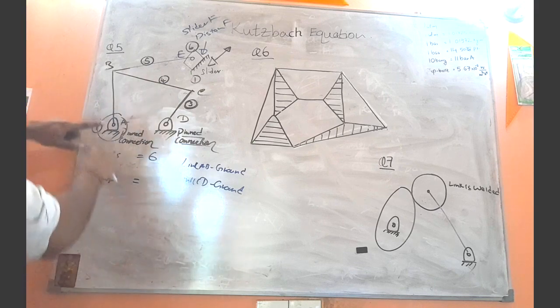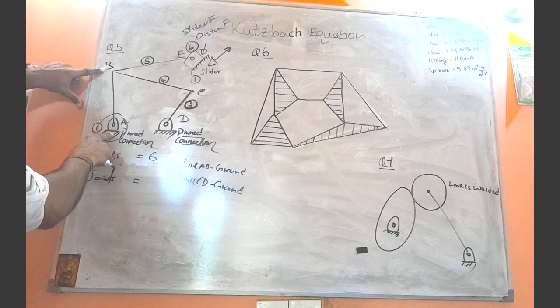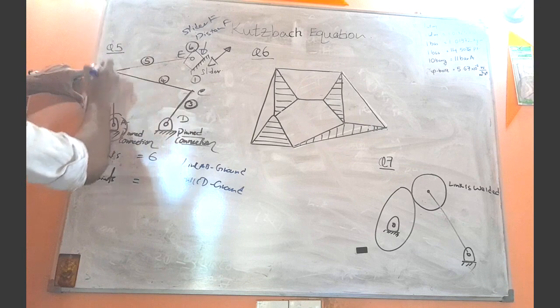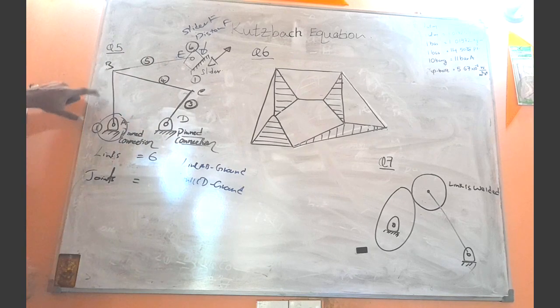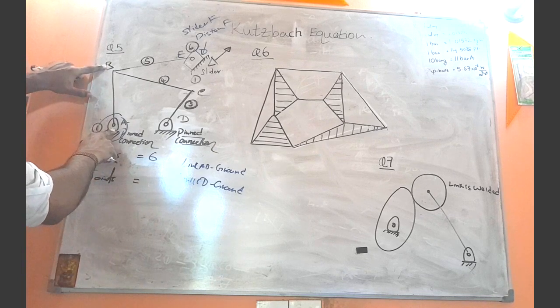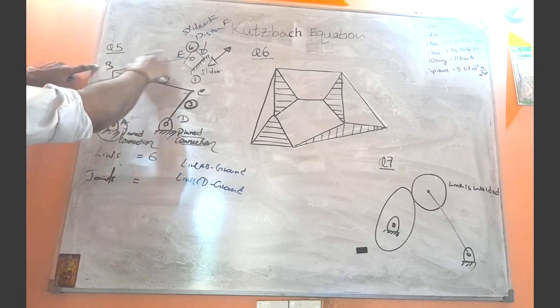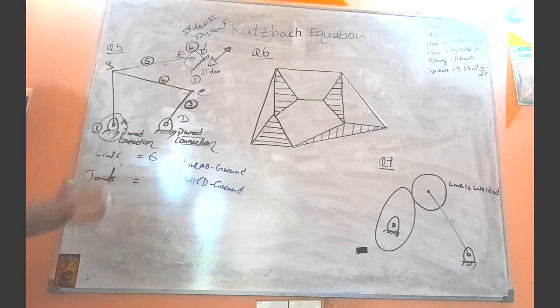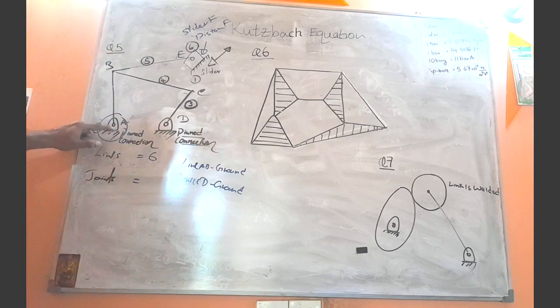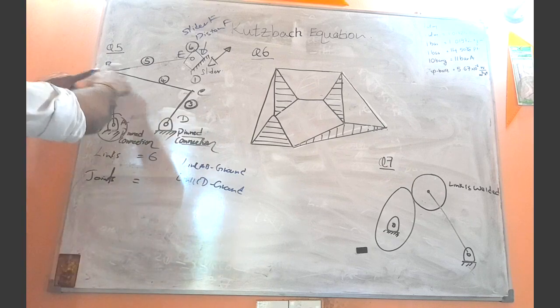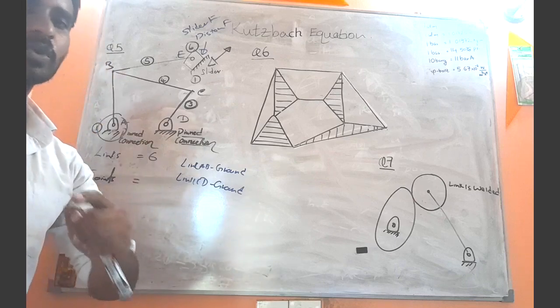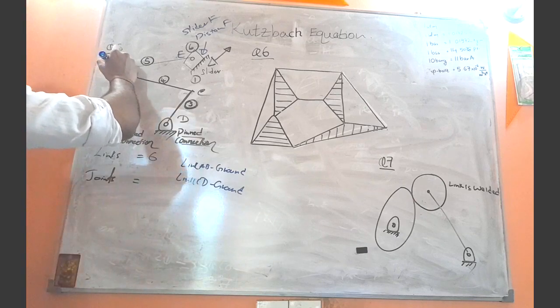Got the point? Now here this link AB is connected to the link BE at the point B, or at the end B of the link AB. Link AB is connected to the link BE at the junction B. So here we have one joint. But not only that, the link AB is also connected to the link BC. So here we have to consider that there are two joints, not only one joint. So here we have two joints, 1 and 2.